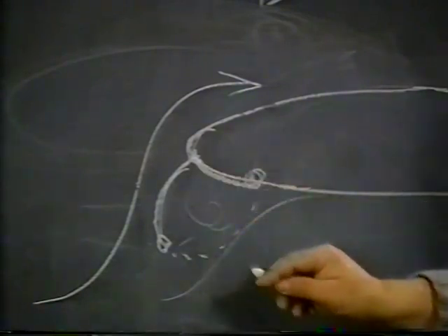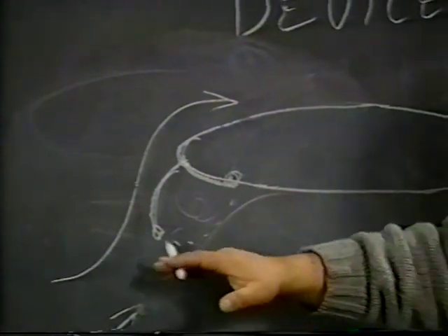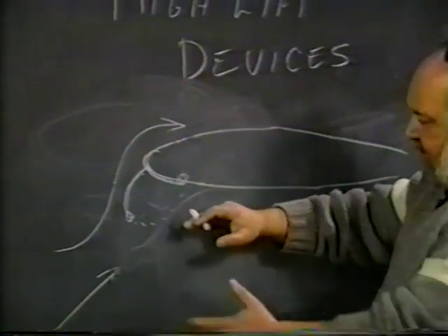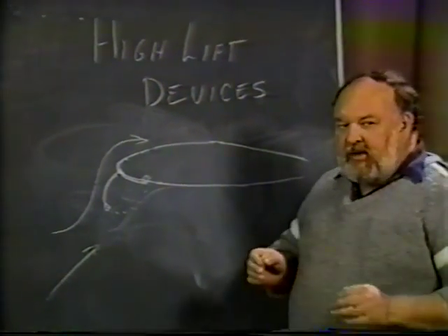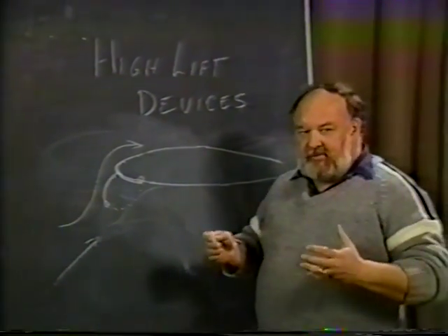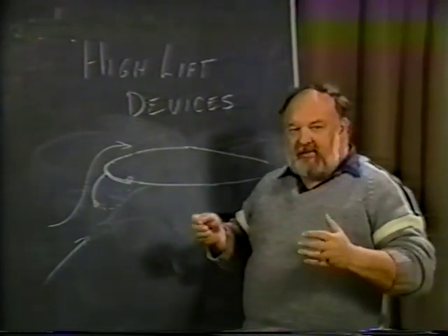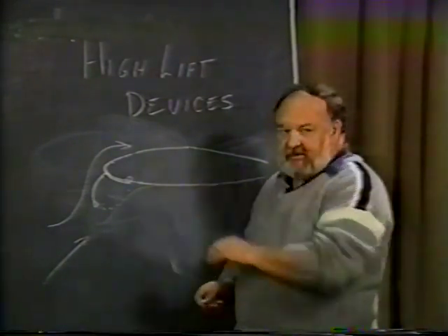The Krueger flap will have a flow separation right behind the leading edge in here, but as the flow comes on the bottom, this separation will not be bad, because what it's actually going to do is be pushed right back up to the surface and flow along the bottom of the wing. You actually can feel turbulence within the airplane when the Krueger flap, the leading edge flap like this, comes down, and there will be some vibration, but it's not a situation of flow separation like you have over the top of the wing.